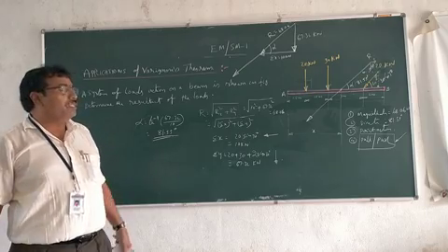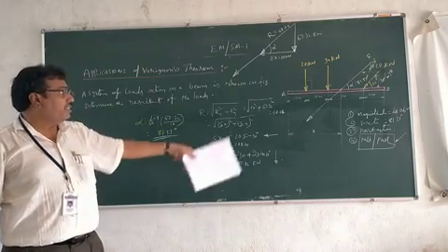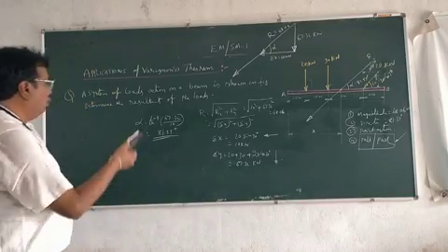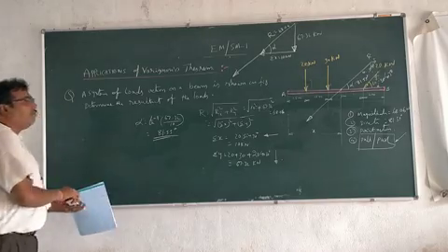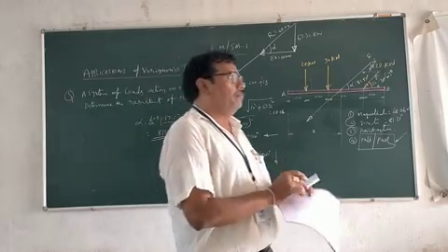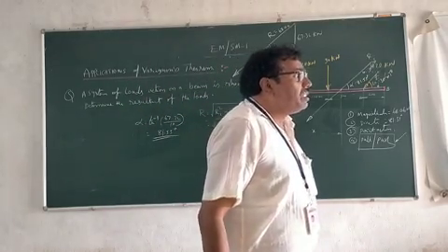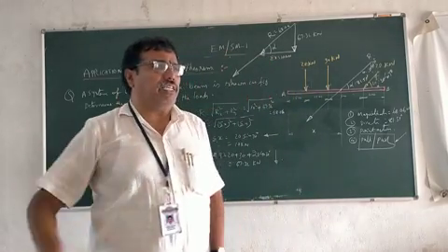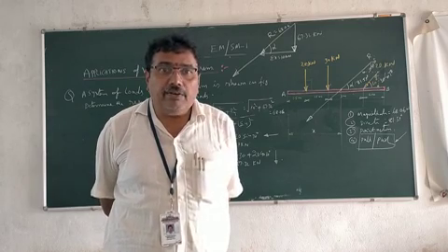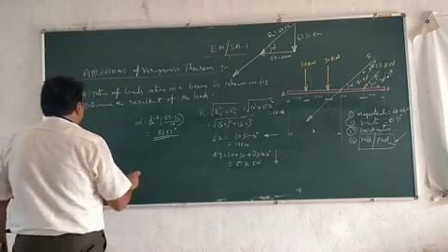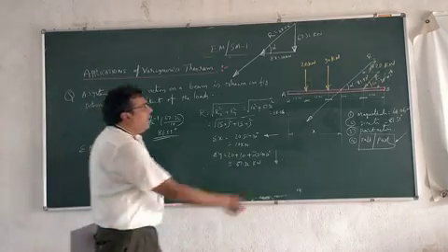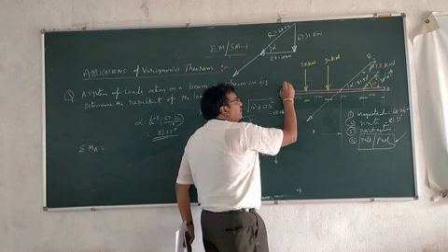For this purpose, the general method is easy for us, but here the Varignon theorem is very visible. What is the definition of the Varignon theorem? The sum of the moments of all the forces acting on the beam is equal to the moment of the resultant, with respect to a moment center. I take A as the moment center.